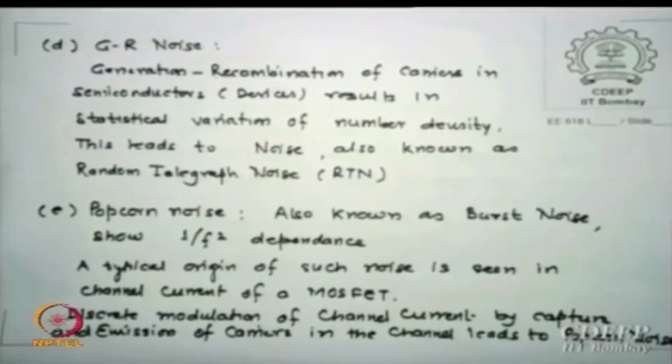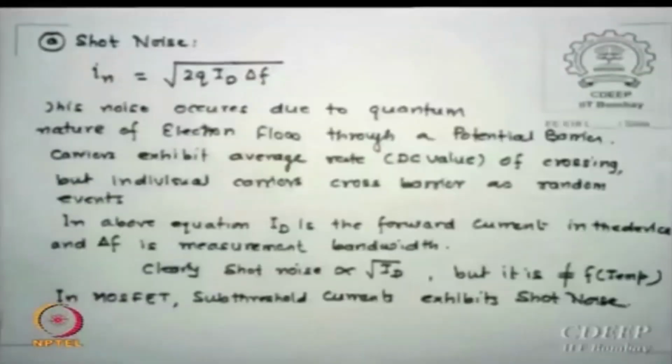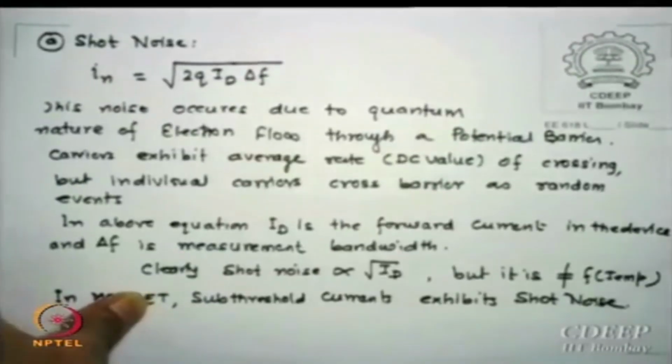So these are some noises, there are a few more but some other day. These are relevant for us, so I thought at least I should talk about our requirements. But in design we do not care so much about popcorn noise because it dies down very fast. So we say that in the most important region of interest this may not be that relevant, but it is not so true that it is not relevant, it is. So let us look at the noise due to components.